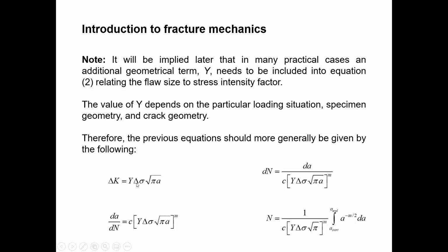Delta K equals delta sigma times square root of pi a. We already know that. If you multiply by Y, that is the crack geometry term, so it governs the crack geometry. If the crack geometry and crack size change, the stress intensity will change. The Y depends on the loading type, such as bending and other types, and on the specimen size.